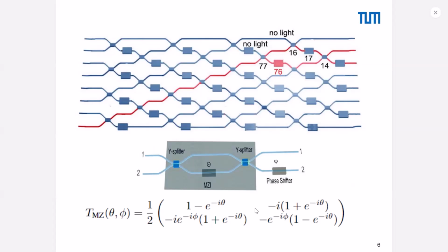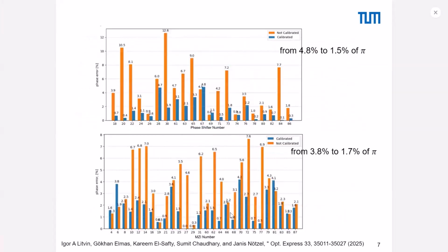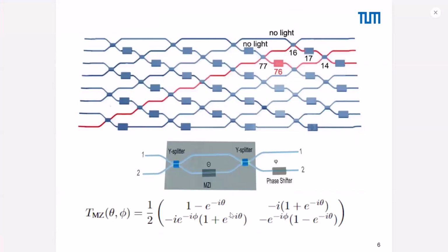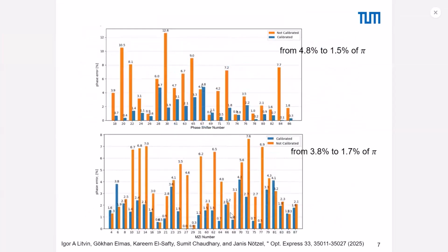For this, we solved the problem by creating so-called effective MZIs. So we created a scheme here. This is kind of an effective MZI. It consists of actually 4 MZIs, 7, 7, and 14, with MZIs in the 50 by 50 setting, so it's pi over 2. And then 2 MZIs are in the bar setting. In this case, we are now able to recalibrate phase shifter 76, which is the external phase shifter. And now we actually have intensity modulation, and we recalibrate it.